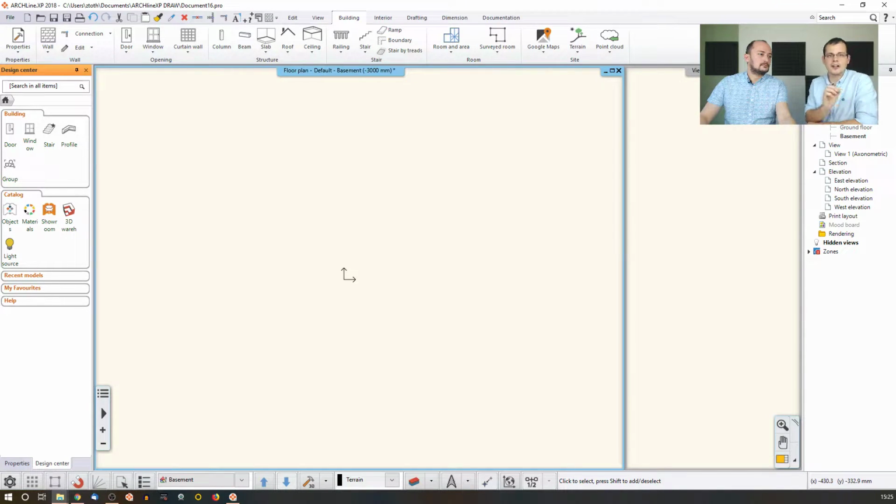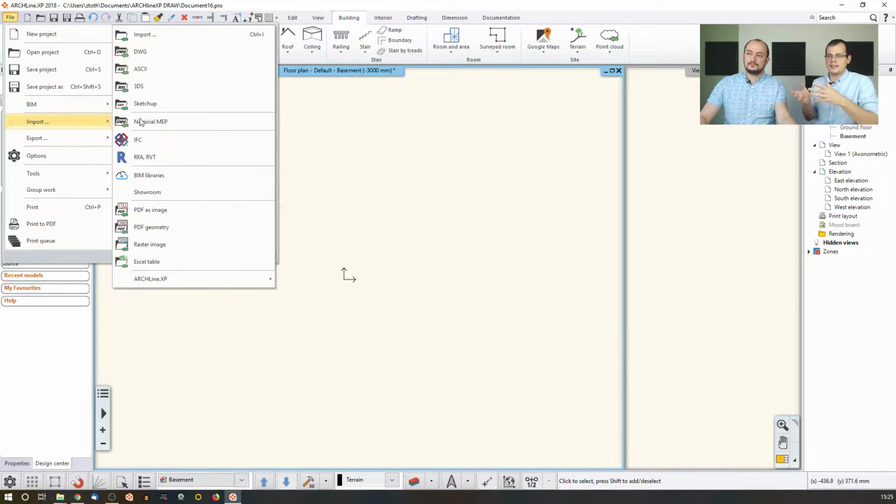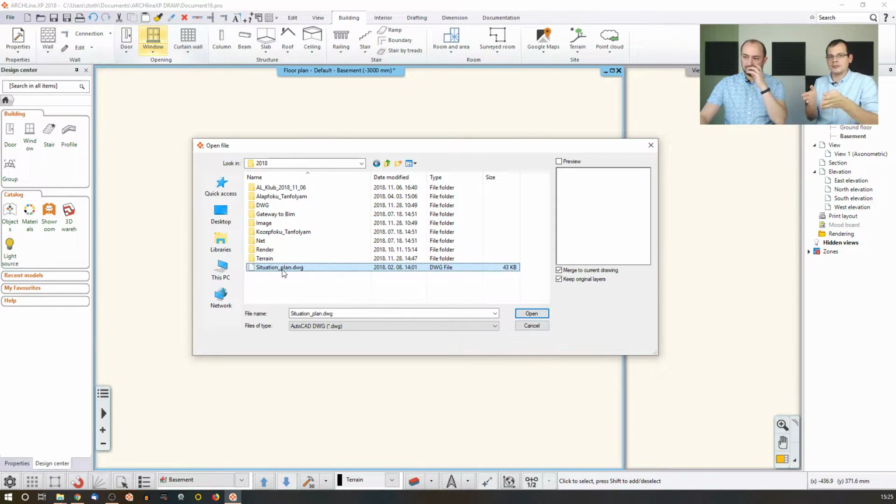We just have to tell the software which lines to pick, which lines to use to create a three-dimensional terrain model. Because once we get that model going, we are able to add the plateaus, the roads and zones and all other things. But the point is that we have to get that line work into the system, and then make the system identify the lines, because it's not able to differentiate from one line to the other. We have to tell it which lines to work with.